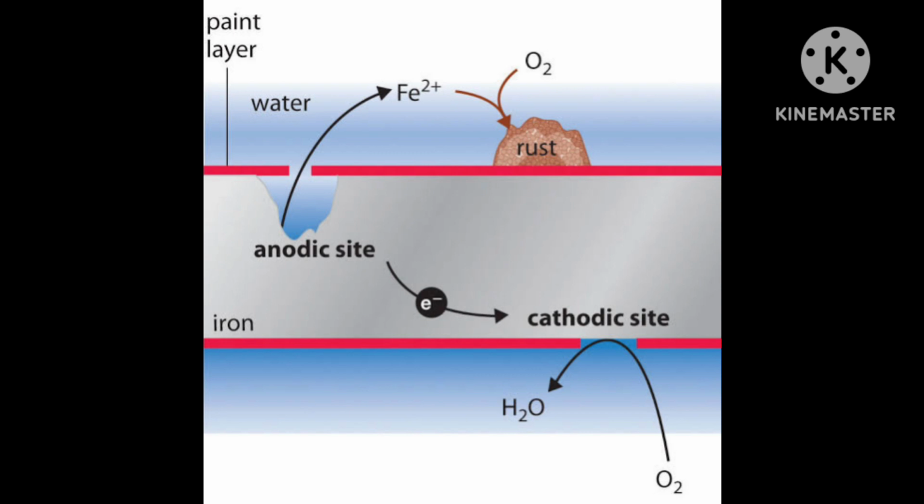With the dust, air will go, and with the air, moisture will go. Again the same thing will happen, because air and moisture are there, and in a corner there is a lot of dust. Then corrosion may start there. That's why even a costlier instrument can be rusted and corroded.